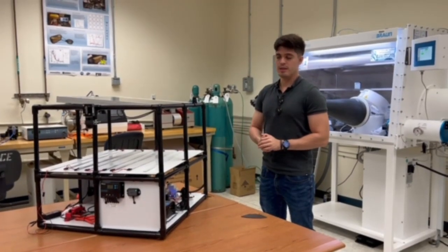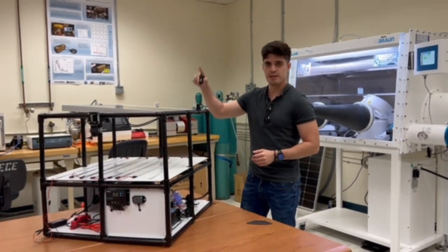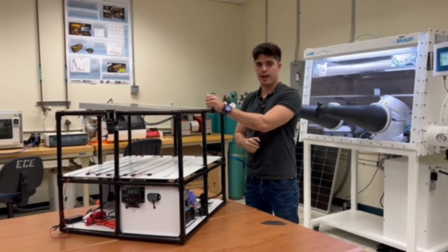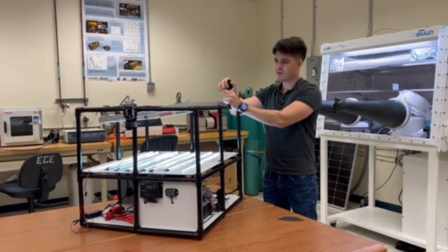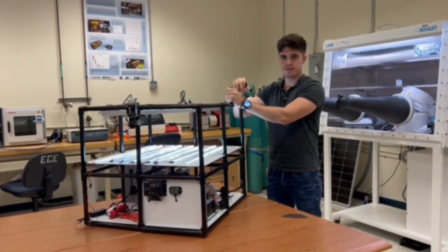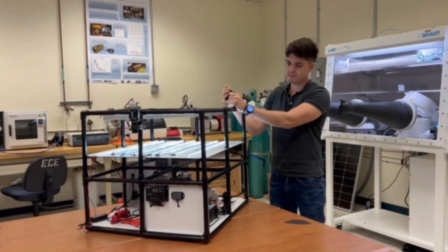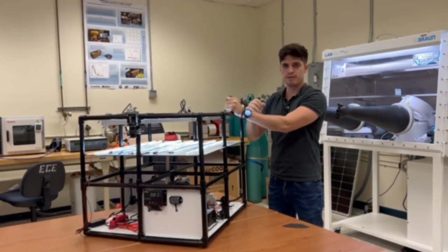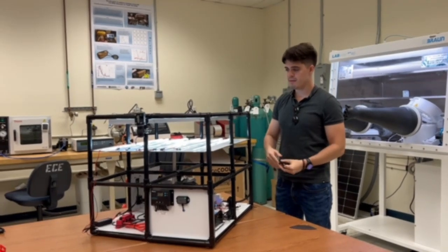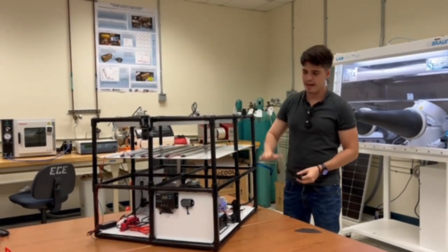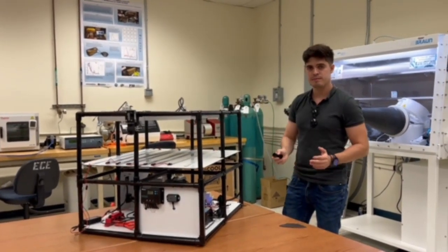The way that our system works is depending on the reading from the photoresistor. In a daytime situation, the solar panel is getting energy from the sun, and during a nighttime situation, simulated by my hand covering the photoresistor, the panel will switch and then get energy from the LEDs in the system. It does so by flipping the panel and then raising the actuator to better receive the power from the light. And then during daytime, again, once there's sun back out, the actuator drops, and then the panel once again flips to receive the energy from the sun.